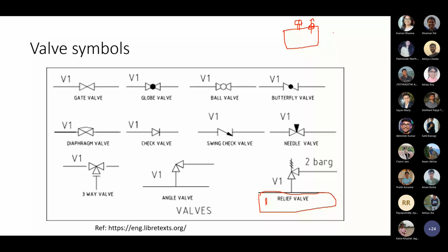They have the storage tank. From this, the vapors are coming, and those vapors cause the whole issue. Ideally, vapors which are hazardous to the environment or human beings should not be released this way. Whatever vapors are emitted should go to another tank and be stored. That is what is often done in various industries. If the vapors are very hazardous, the relief valve should connect to some other process vessel where the vapor can go and be stored. But they don't have this storage tank.